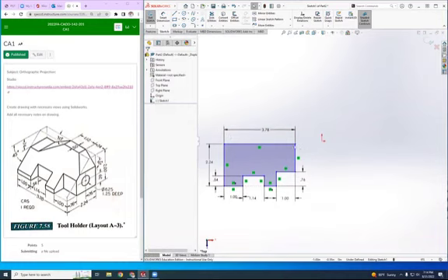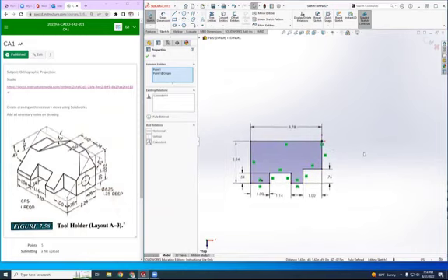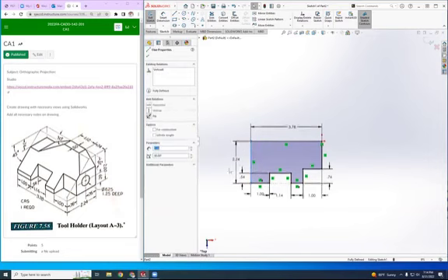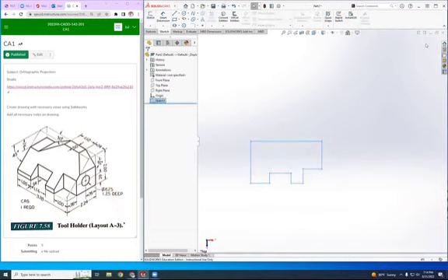What point should be pinned to the origin? Technically, it can be any. But if you took my intro class to SOLIDWORKS 139, you know that some points are more important than others. So coincident. Need to do the coincident. I'm going to make that coincident to that top corner. Now my sketch is black. Now it's fully constrained. Try to skew it, try to move it. It's impossible. So that's what you want, fully constrained sketch. You close the sketch using the arrow, not the X.